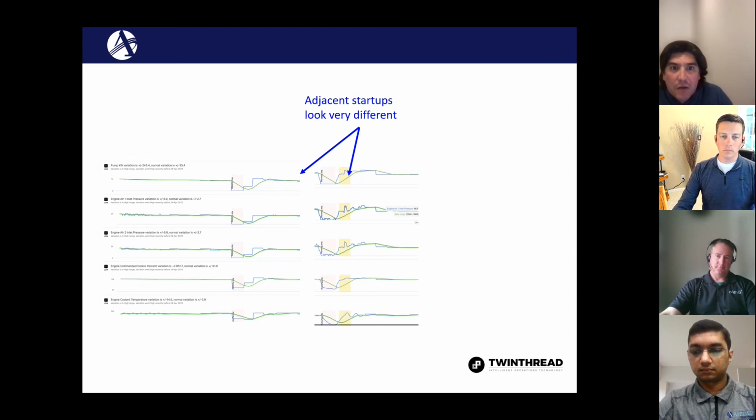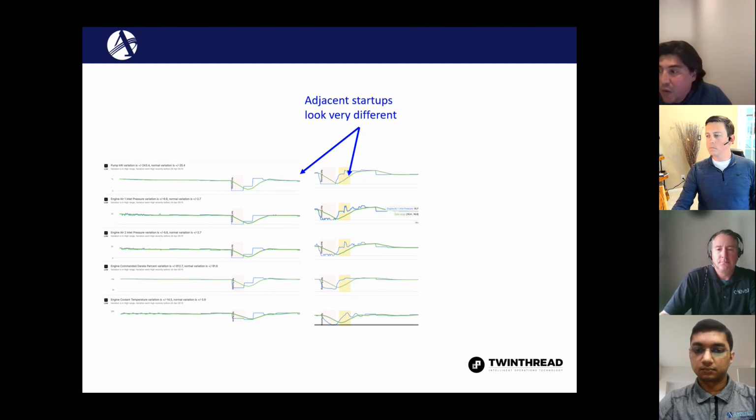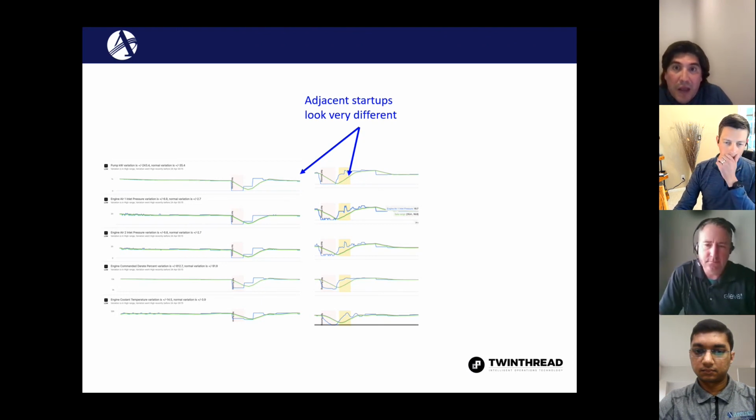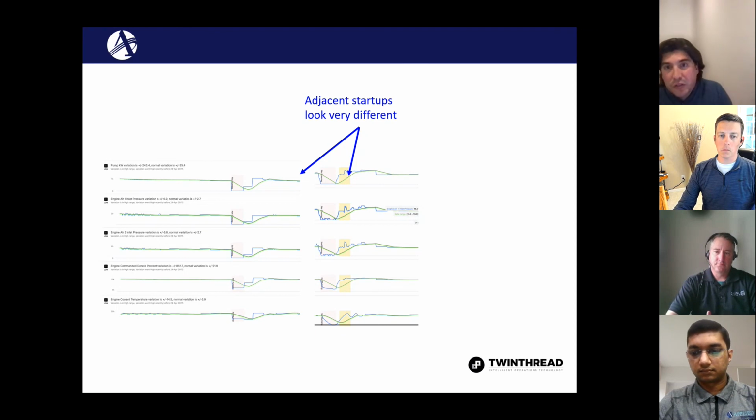And there's different ways that we can do that. We can create a workflow that sends text messages or emails directly to a field service engineer to make a change. We can integrate with existing maintenance systems to kick off a work order and order parts ahead of time. Or in some cases, we can even close the loop and connect back to the PLC and make changes directly on the control system.